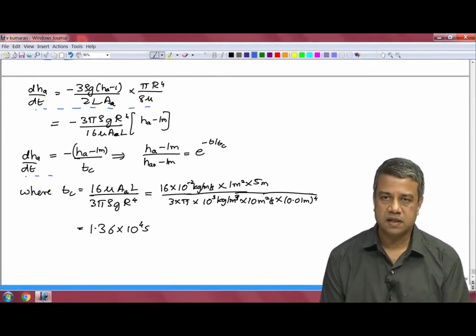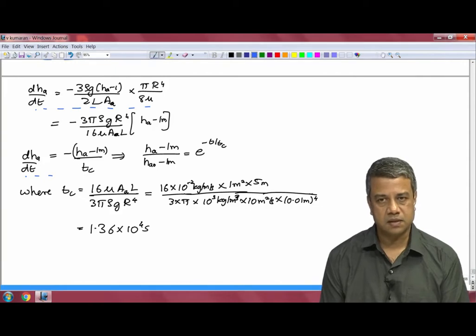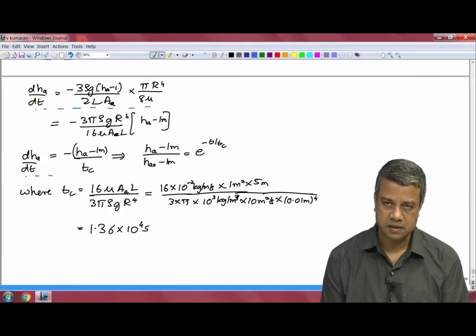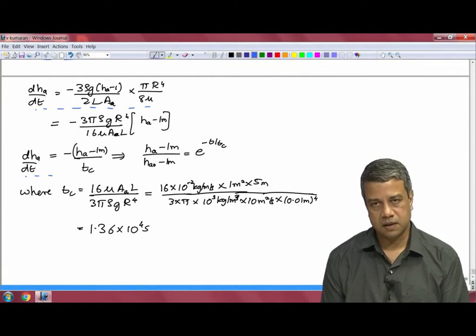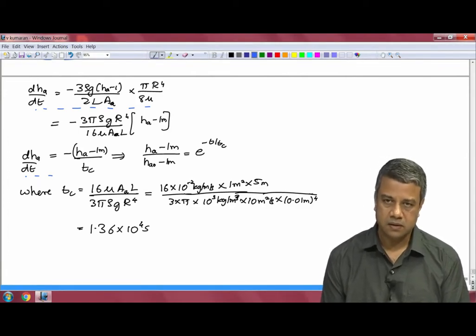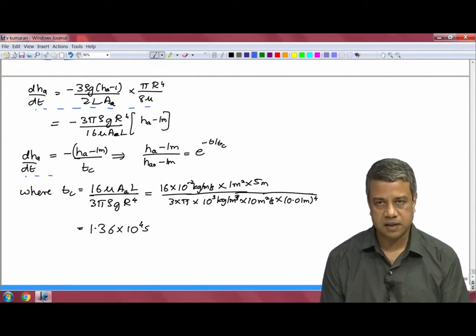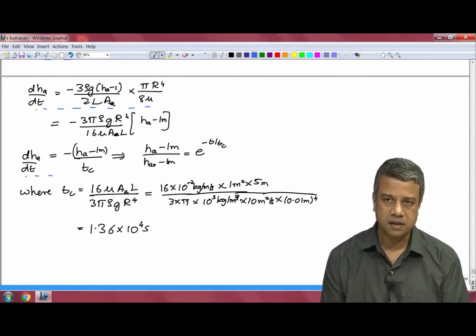In the final steady state, the total volume of fluid in the tank is initially 3 meters cubed, because the area of tank A is 1 meter square and the height was 3 meters. Final height is 1 meter in both tanks. Tank A cross sectional area 1 meter square, tank B 2 meters square, total is 3 meters square times the height 1 meter is the volume.